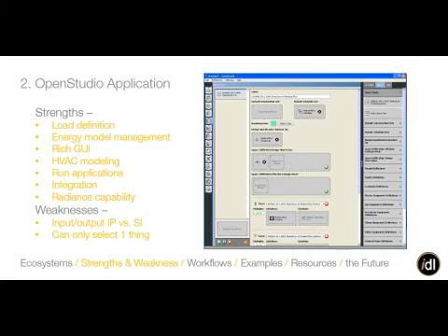If we had a project come in through Revit, we could export it in. How much time do you think that gap is, you said double the time versus half? Do you think that gap is smaller if you start with the Revit model? Yeah, depending, it can be. Although, really, if you're going from Revit to this, depending upon the experience of doing the gbXML exports, sometimes it's easier just to remodel it in SketchUp, and that can be really quick as well because it's very simplified thermal zone modeling. Still, starting from Revit, doing HAP versus doing OpenStudio, it's probably still going to be a little bit more time.